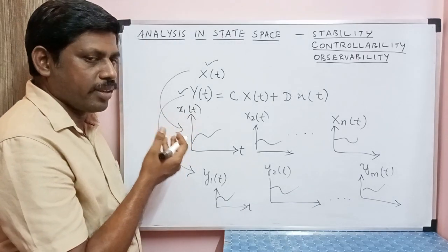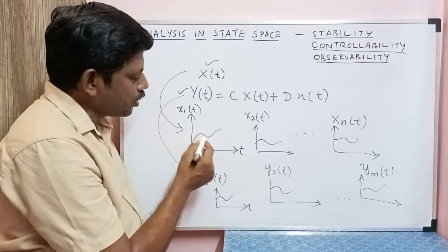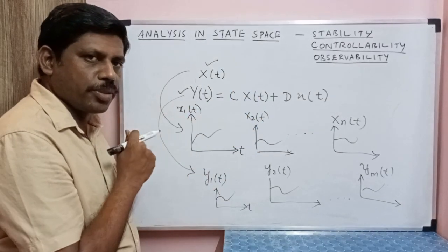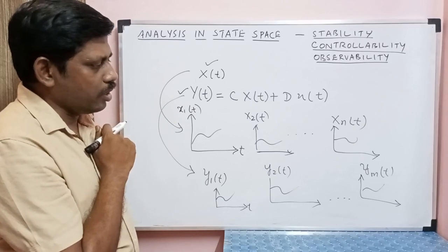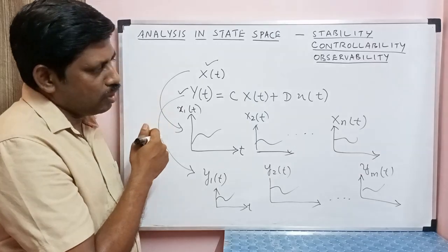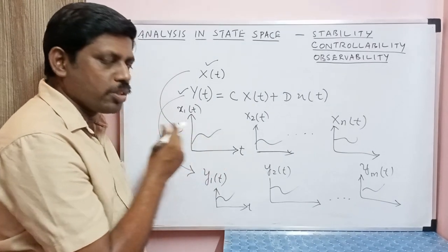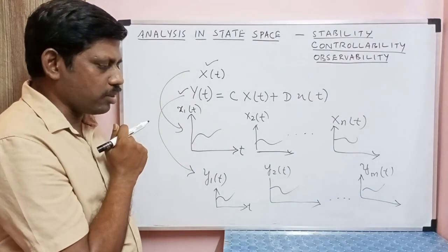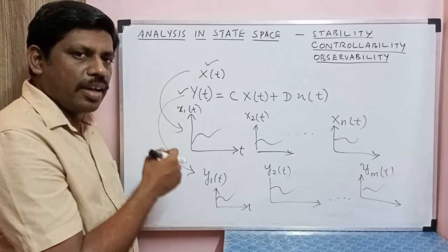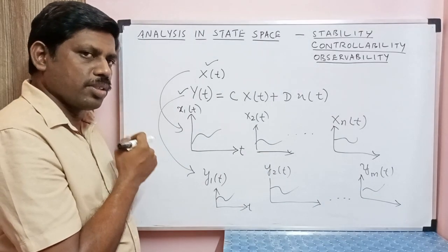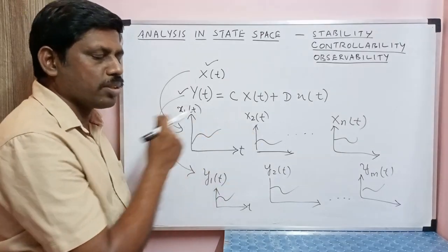For example, I can analyze whether the system is going to be stable, what the rise time is going to be, what the peak time is going to be, what the settling time is going to be, and all those things I can understand. Even if an analytical solution is not possible, I can get these plots by numerical integration of the state equation, and once I get these responses, I can analyze the system. Especially, I can analyze the stability of the system by looking at the responses.